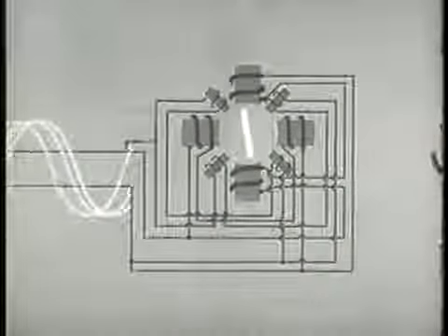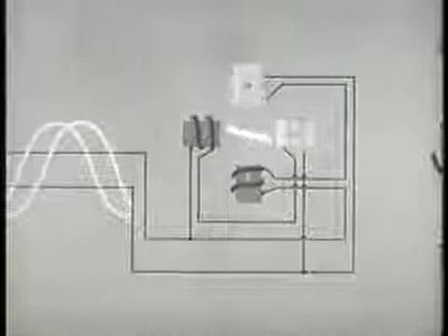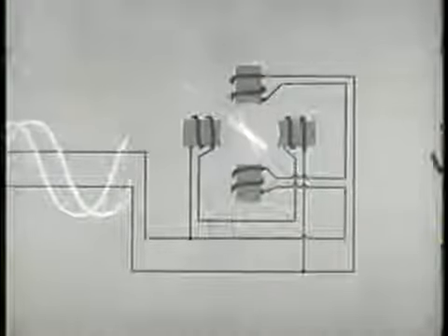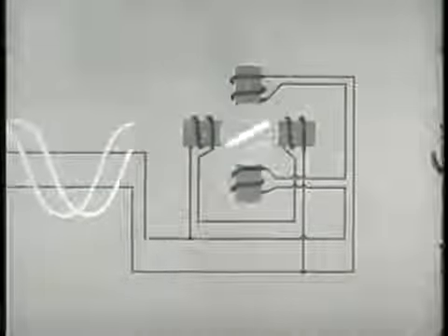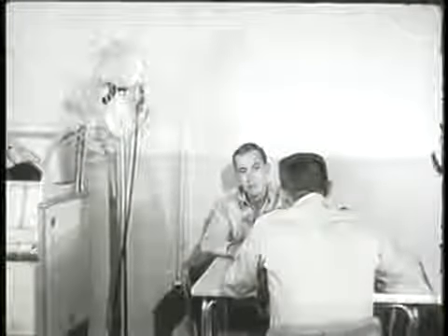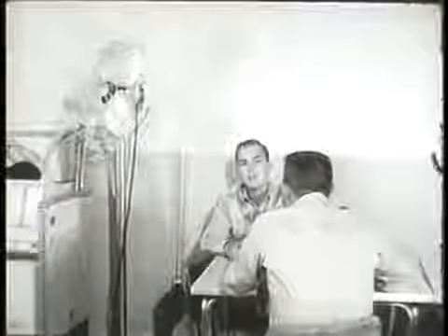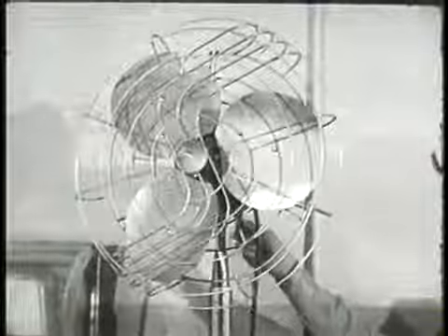When the rotor has attained approximately 25% of its rated speed, a centrifugal switch opens and disconnects the starter windings. The phase shift accomplished by the addition of starter windings is not very great. The starting torque in this split-phase arrangement, although better than that in the shaded pole motor, is still not too good.